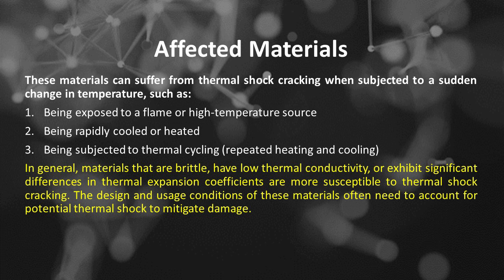In general, materials that are brittle, have low thermal conductivity, or exhibit significant differences in thermal expansion coefficients are more susceptible to thermal shock cracking. The design and usage conditions of these materials often need to account for potential thermal shock to mitigate damage.